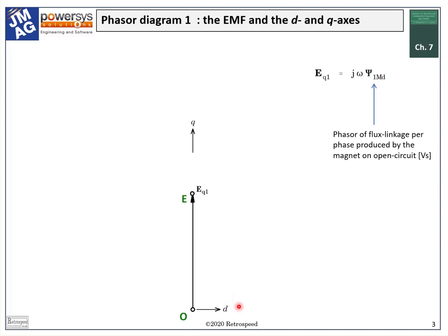In fact, the D-axis in electric machine theory has always been the main field axis, originally aligned with the axis of the field winding. This is the case not only in synchronous machines, but also in DC machines. In our case, the surface magnet brushless motor is a synchronous machine, so there's every reason to follow this principle.